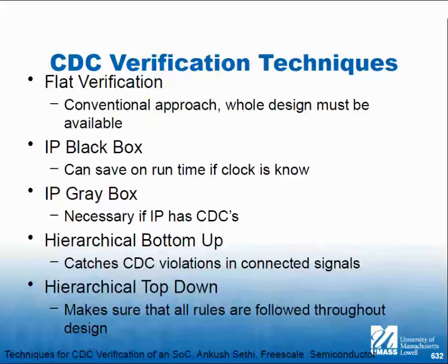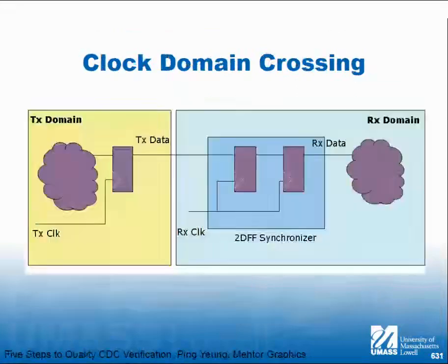There are tools, by the way, too. So these tools like Lint and like Spyglass that are code checking tools will flag a lack of clock domain crossing. They might say it a little differently. They might say there's logic here, right? But you have to read that as you have to go through 2 flip-flops before you can go to logic.